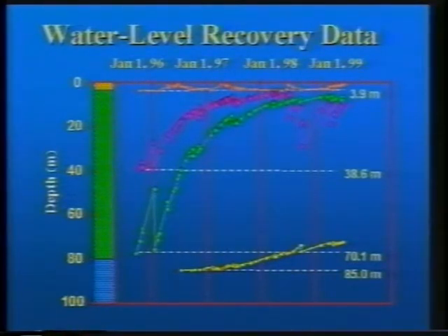The two piezometers that are completed in the till, the pink and the lime green, are representative of the till responses, and you can see that they are very similar. Slow responses, low hydraulic conductivities. Compare that to one of the responses for the clay aquitard, the yellow recovery. Ultimately, that yellow recovery, when it comes to equilibrium, will be less than 2 meters below ground surface, so it still has a long way to go. The hydraulic conductivity is much lower for the clay aquitard than for the till aquitard. Over the last 5 years since installation, the piezometers in the clay aquitard have responded to the tune of 10 meters, so they're responding very slowly.